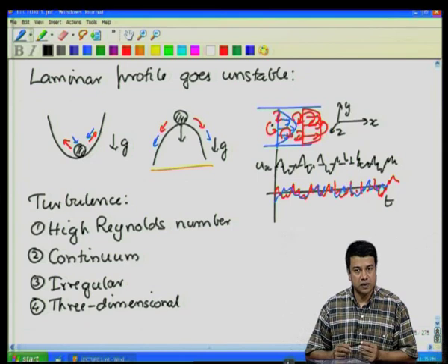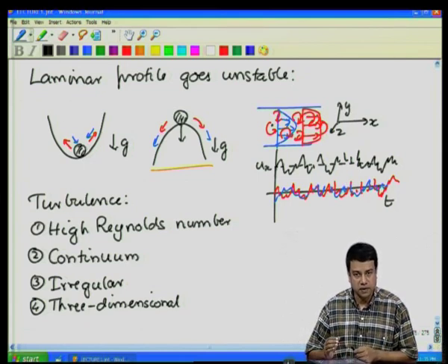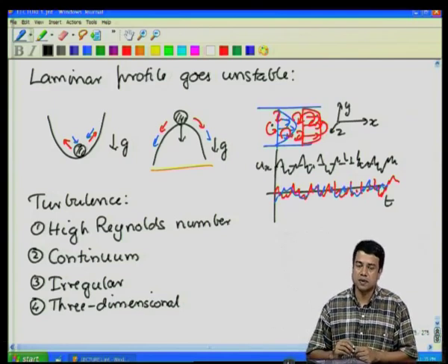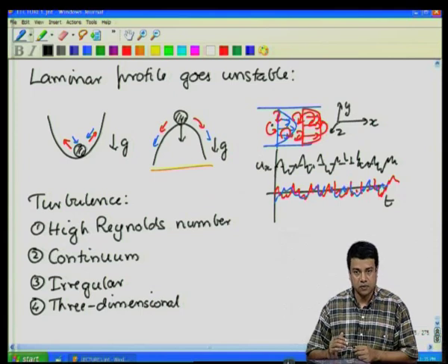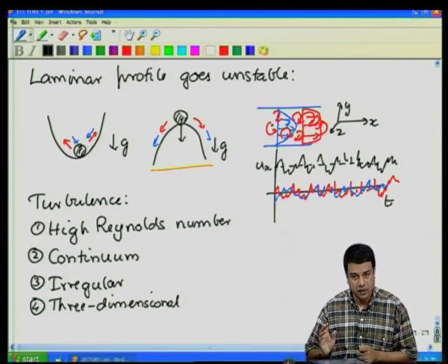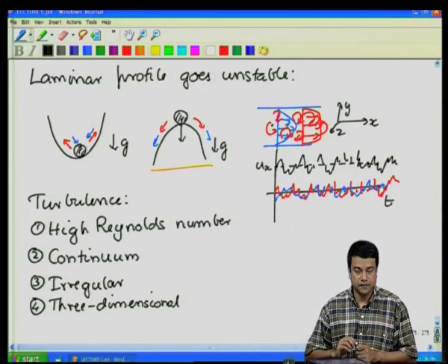If you recall, when we did vorticity dynamics, I told you that vorticity of course diffuses by a mechanism similar to viscous diffusion. However, it is also intensified due to the stretching and bending of vortex lines, in a manner similar to the change in material line elements due to the gradient in the velocity.